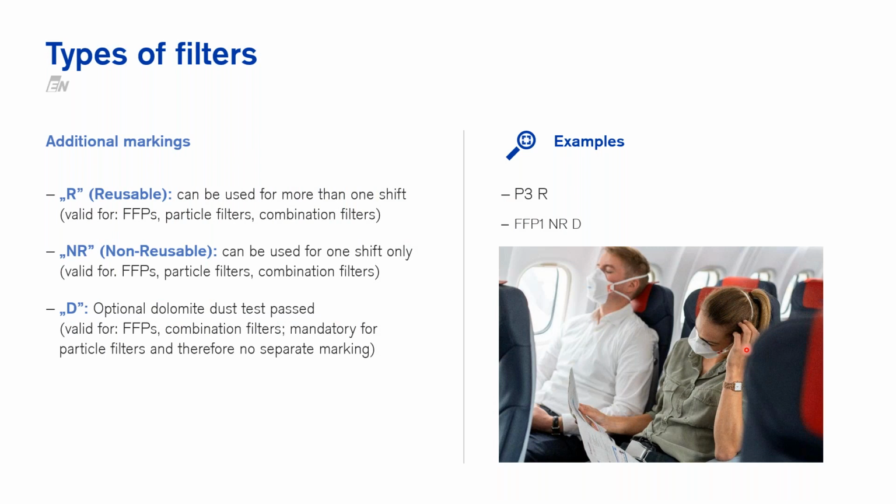The performance tests included in this standard are the filter penetration, the extended exposure test, the breathing resistance, and the total inward leakage, which I mentioned just now, which evaluates the filter penetration, the valve leakages if there's any valve, and the most important, the face seal leakage of the respirator. So this is taken into consideration compared to N95 or NIOSH standards. This is not really being tested.